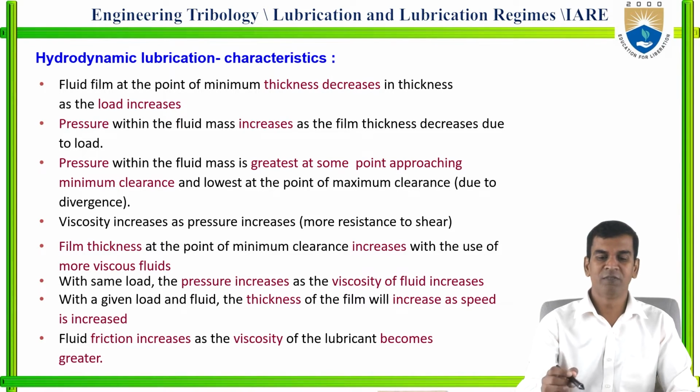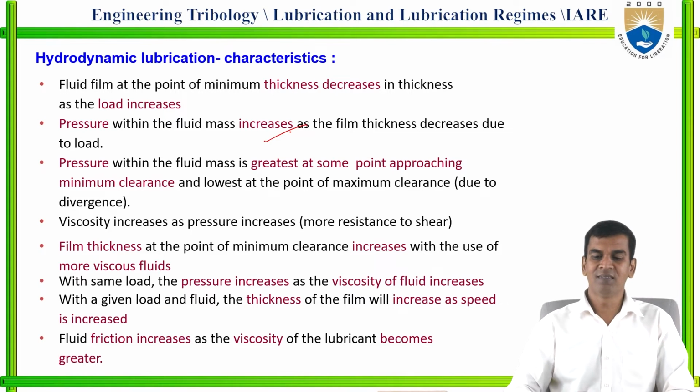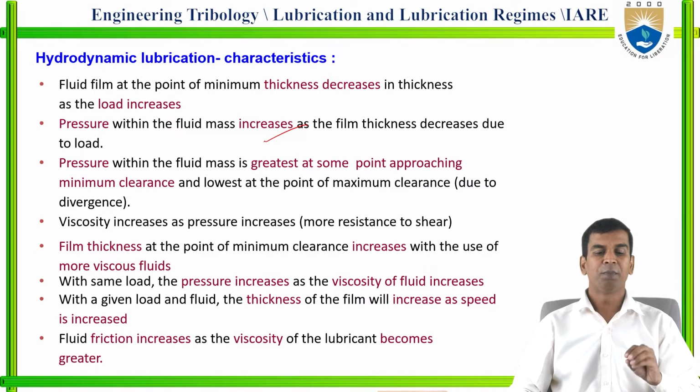The pressure within the fluid mass increases as the film thickness decreases. Okay, when the load increases, film thickness decreases, and when the film thickness decreases, pressure inside the mass increases.